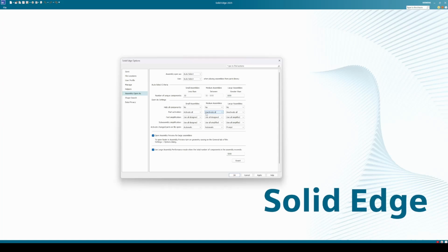It's not going to process the inactive parts. Just keep it in mind, if you are limited in computing resources, then for the components you're not using, make them inactive. So it's just easier for your computer to compute all the files and update your models. Keep that in mind, but you can change it as is.